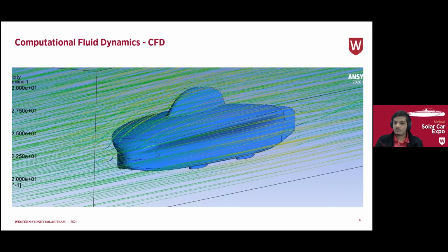Once you do have a good result, what you can do with it is pretty incredible. The main things I use to analyze an aerobody's performance is to look at the various forms of pressure plots to see if there's separation occurring or if unnecessary forces are acting on the body. We can also visualize vortexes and other turbulent flow generated around the car, and quite often can track back to what part of the car is actually generating it. Using this and many more results variables, we can compare iterations of a design and evaluate if the changes made were good. Over many iterations of CAD and CFD, we can end up with a highly optimized solar car that produces very little aerodynamic drag.